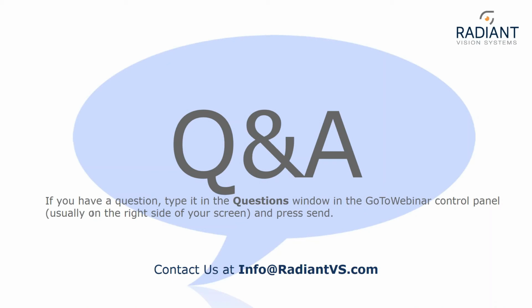There's another question here. Is a Mura defect caused by non-uniform display luminance? A Mura defect is more caused by a non-uniform response of the pixel over gray level compared to the surrounding pixels. That is why it is important to characterize the response of every pixel within the display to drive them to the same correction curve.